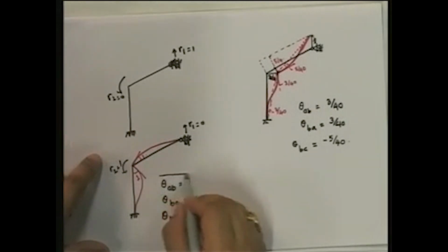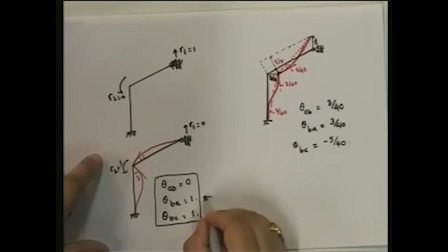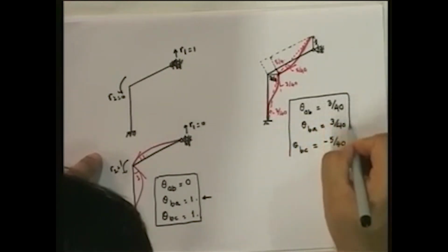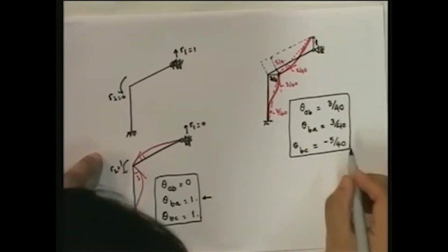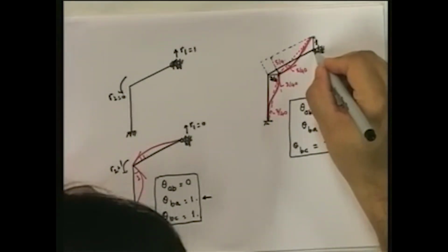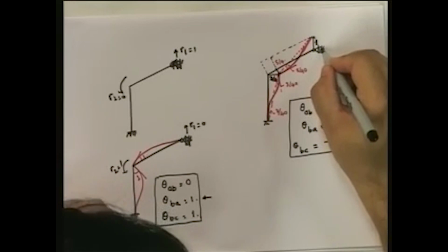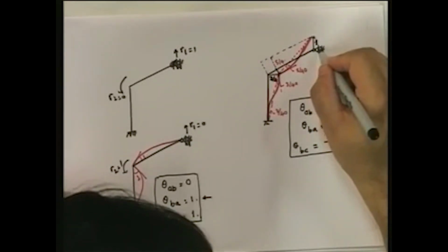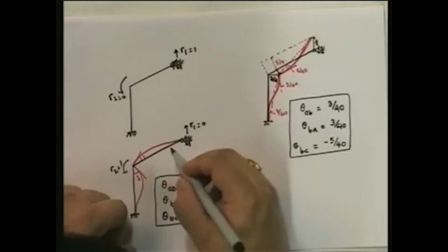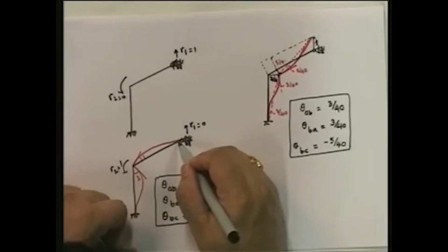Note something very interesting, that if you look at these values, the fact that this point has become a hinge and not a fixed roller, it is a hinge roller and not a fixed roller as earlier, has nothing to do with the shapes, excepting for the fact that at this point you do not have zero rotation.